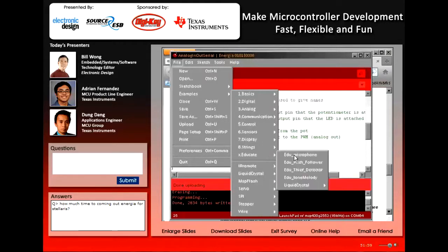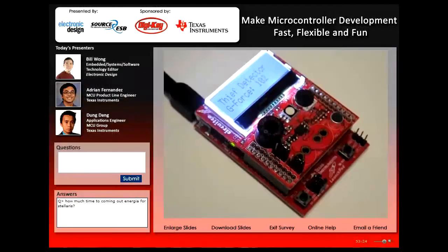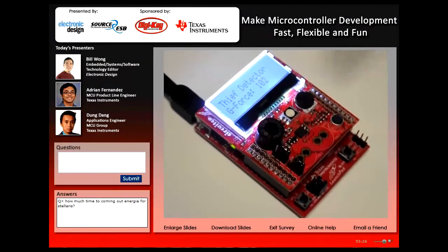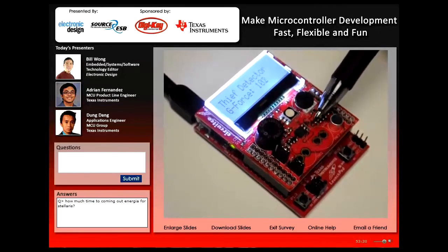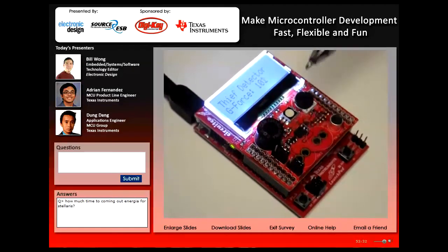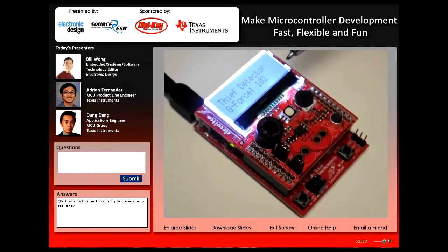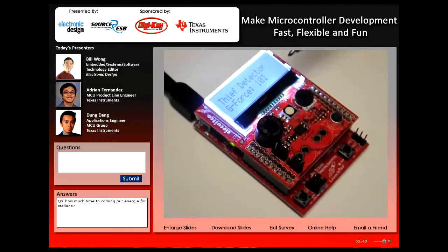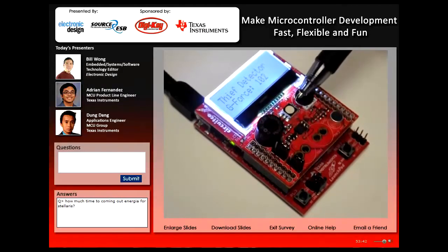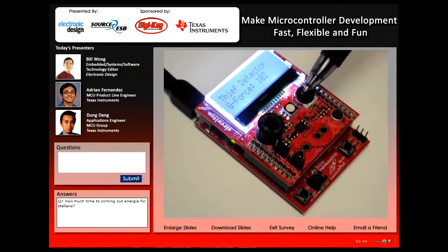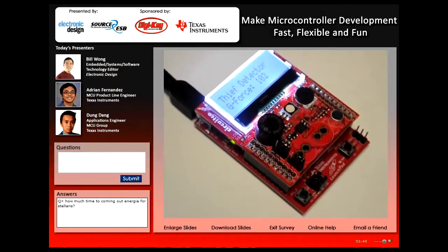And what this example does is that it takes in the accelerometer. So as you can see, when first loaded, the application reads the values from the 3-axis accelerometer and displays the resultant vector on the LCD screen. When this value increases beyond a certain threshold, it would sound the buzzer and turn on the LED, alerting that a thief was detected. So let's see it in action.